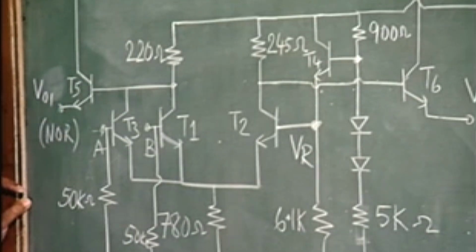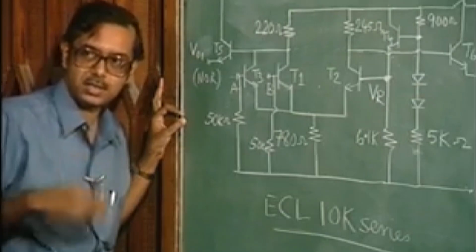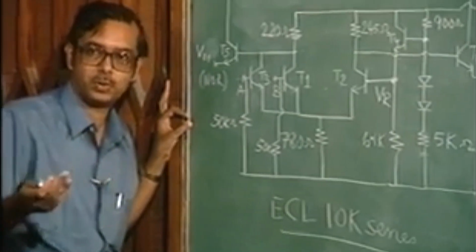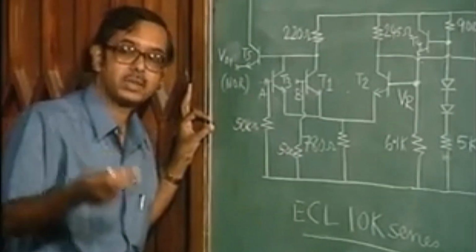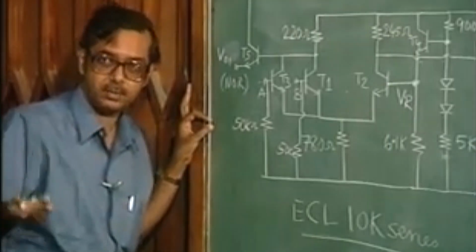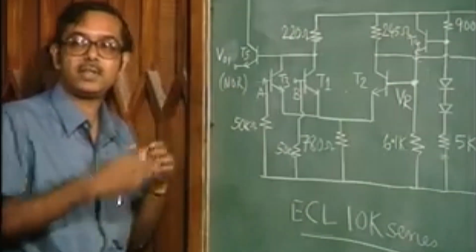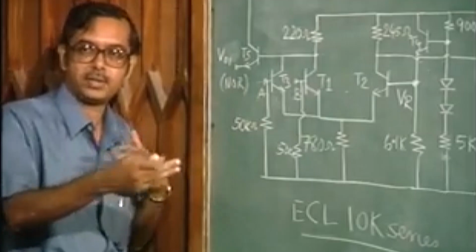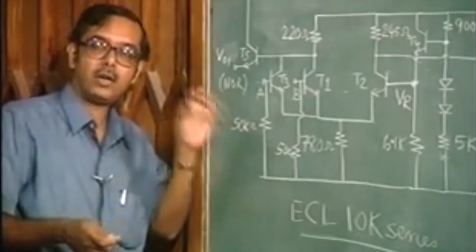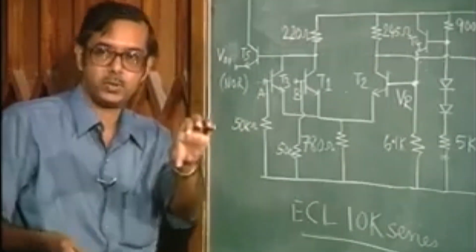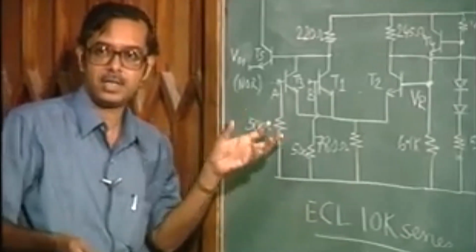And if you have OR or NOR logic, you know that if any input is logic 0, it does not contribute to the output. The output is governed by the other inputs. If you have a 3 input NOR gate or OR gate and one input is 0, the output depends on the other 2 inputs. A 0 does not contribute.